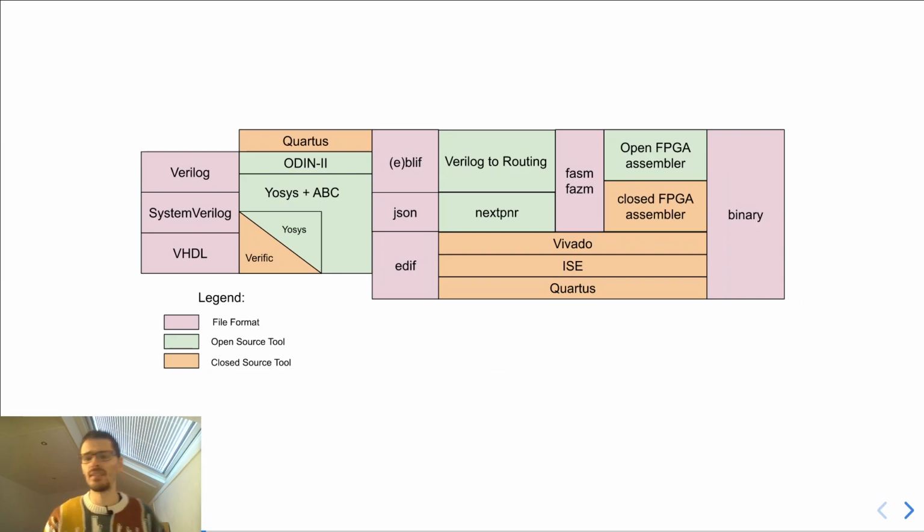So the process of taking your design and making it into a binary for an FPGA is roughly displayed here, where you start with Verilog or VHDL 2020 or whatever you have, and then there are the commercial tools like Quartus, and there's this open source academic project. I will be mostly talking about Yosys and ABC, which then spit out a netlist that you can place and route.